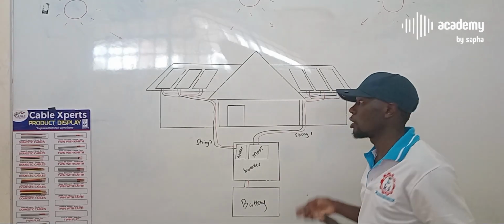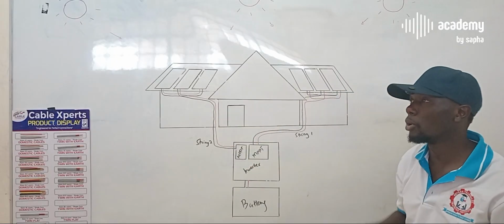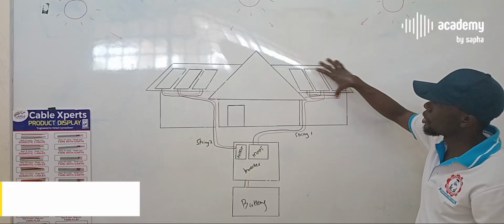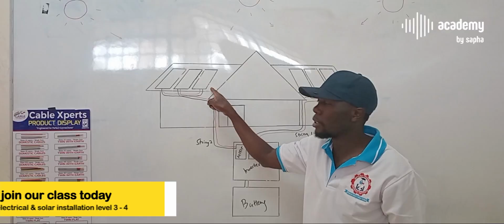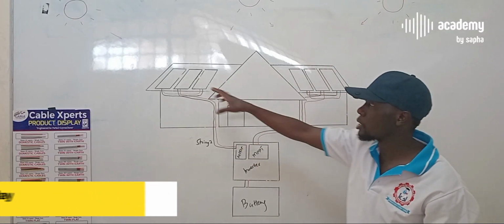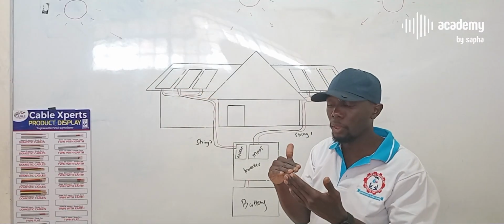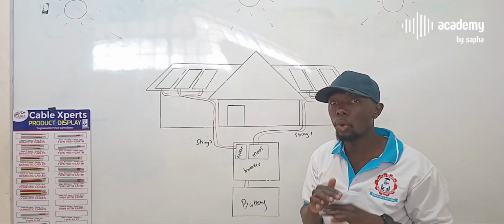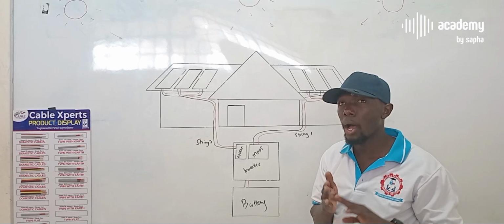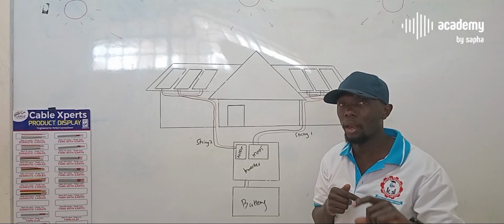The difference is that if you have everything connected together, even in a parallel system, during the morning hours whatever is being generated this way might be optimum, but here we are generating below par. Most solar arrays will perform to the best of the weakest link in the system.